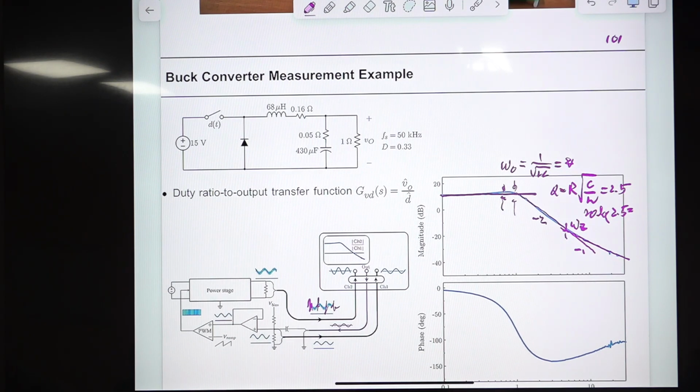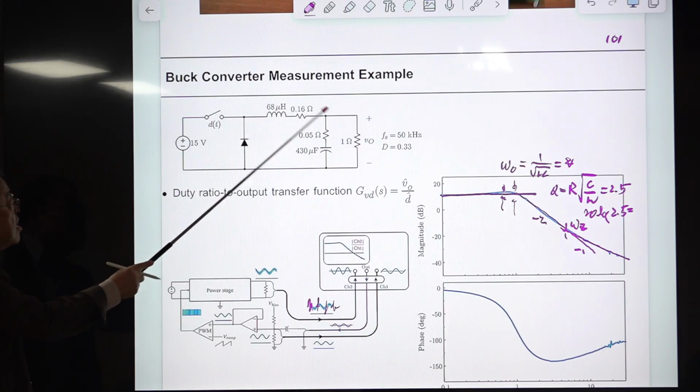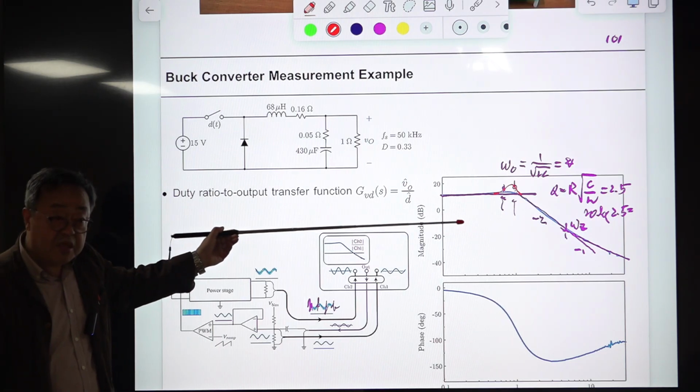This is a hardware measurement. So in hardware, there are many parasitic resistances not incorporated in the analytical, theoretical prediction. In theory, we just considered this and this, but there are other resistance components here. So the damping Q is smaller than the prediction. Maybe the theoretical prediction will be like this, then the measurement should always be smaller than this, right?